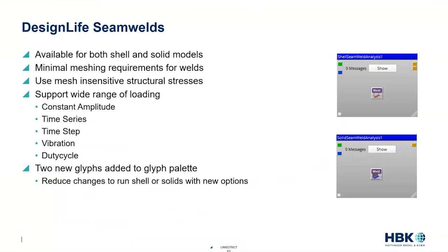And probably as important as anything is they both support a wide range of loading. Again, in terms of fatigue, we're trying to characterize loads on our part over its entire life to prescribe fatigue behavior. And so we have a variety of approaches, both in the time domain that can look at things as simple as constant amplitude loads, but transient loads, loads that are brought in from measured force histories and superimposed.